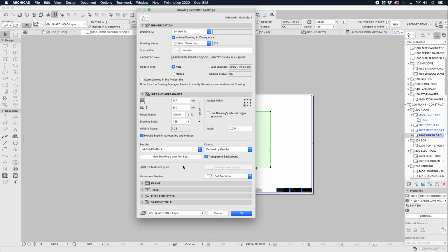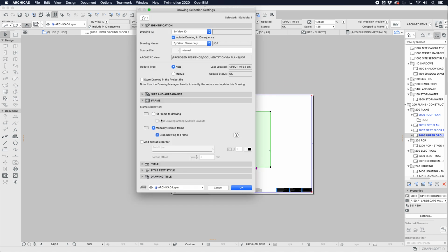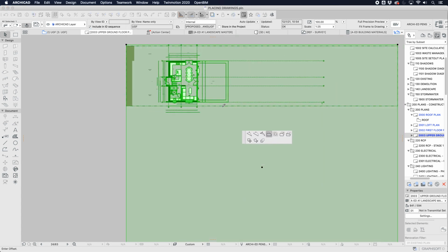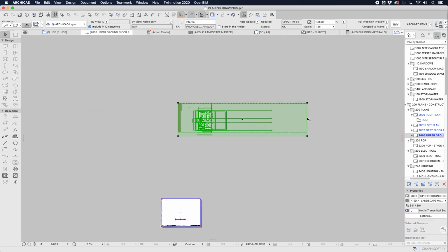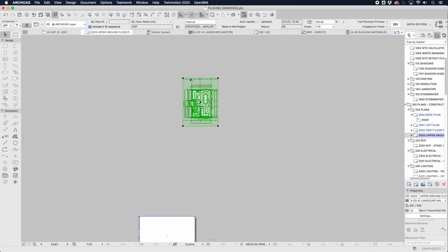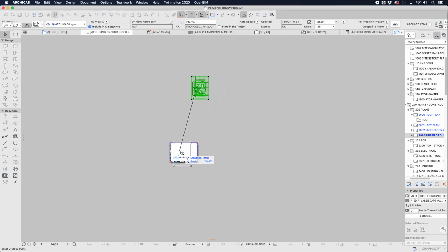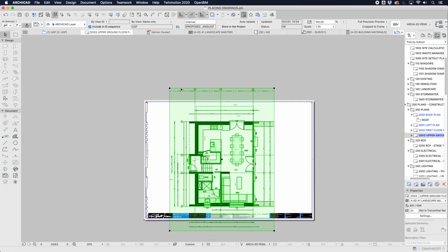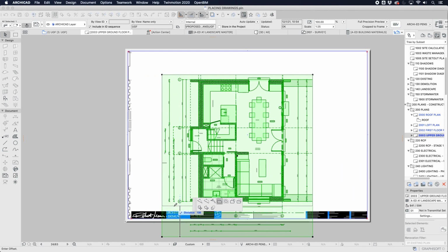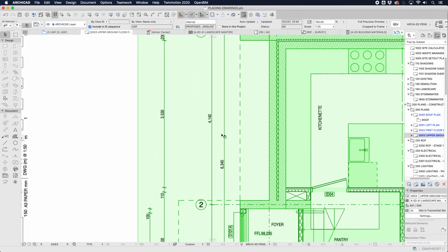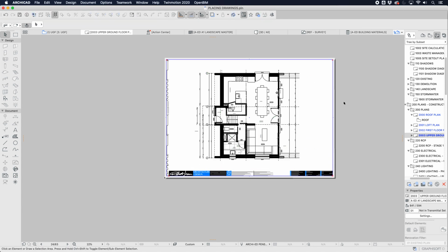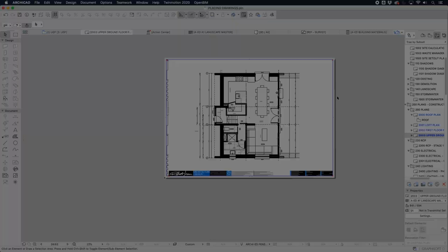And then of course, like before, if we go back to our frame and then choose fit frame to drawing, that's going to allow us to see everything. And then we can just resize this back to where it needs to be. Now what we will find is that this doesn't fit onto our page anymore. So we'd need to have a view that was okay with cutting out all of these dimensions, or of course, we could shrink these dimensions in. We could make them a lot closer together if we decided we wanted to work at a scale of something like 1 to 25 instead of 1 to 50.